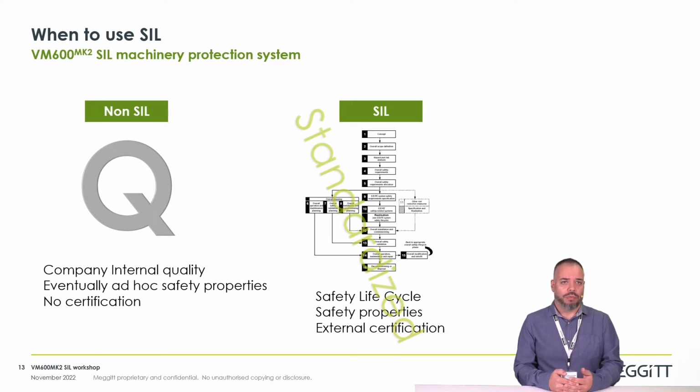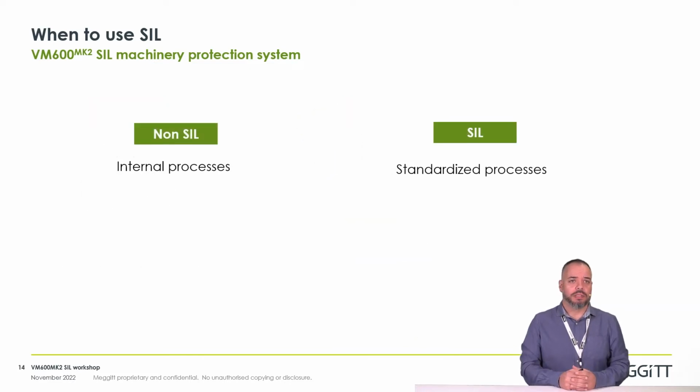While for the SIL one, you know that the entire life cycle is respected. And again, this means all aspects from design, development, production, commissioning and decommissioning. For a non-SIL device, these aspects are eventually also covered, but not in a standard and independently verified way. They will depend mainly on the manufacturer. So, in practical terms, the major difference is that a SIL certified equipment is developed and operated based on a standardized process, as we saw, while a non-SIL one may follow quality standards, but not necessarily the ones dedicated to functional safety.